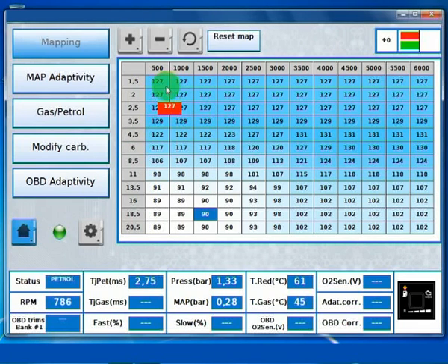We calculate this map during the auto calibration, and you can change it later if you need to make some adjustment. The auto calibration does not cover all the times and all the sections of the map because it's made on idle, so we don't have all the information about how the vehicle is running in all conditions.